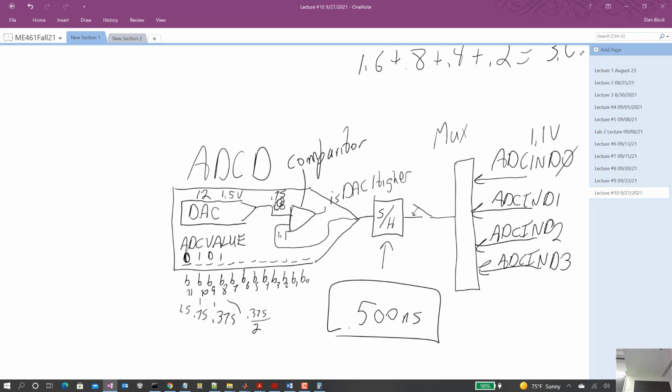What happens if the input signal is changing? How does it decide what part of the thing to convert to? Okay. So remember what I said, we're going to set up EPWM5 to time out, initially, every 1 millisecond. Okay? So at that moment of time, at 1 millisecond, and I kind of drew this a little wrong, each of these has its own sample and hold.